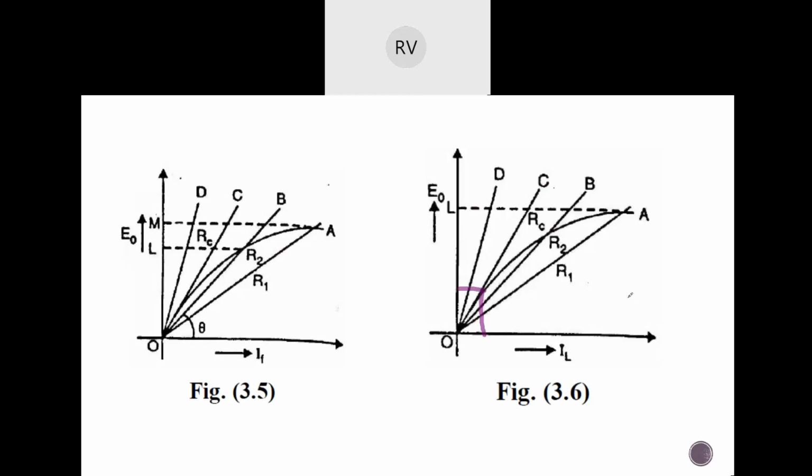So what we'll be doing is drawing a tangent to the OCC, which is going through the O, that is the origin. And then we'll find out the point at which the tangent cuts the OCC, or where it touches the OCC, and from there we'll find out the critical field resistance that is required for the voltage buildup. Okay.